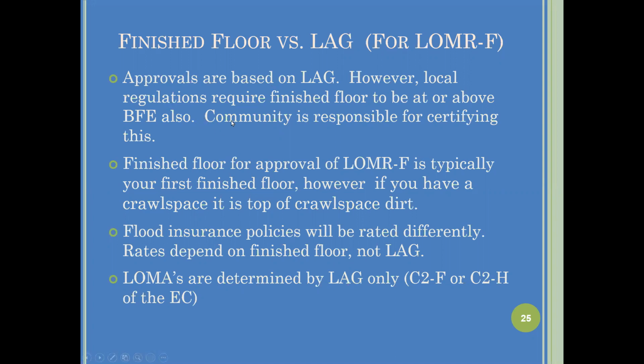Finished floor for approval of LOMR-F is typically your first finished floor. However, if you have a crawl space, it is the top of that crawl space. And flood insurance policies will be rated differently, and the rates depend on the finished floor, not the lowest adjacent grade.